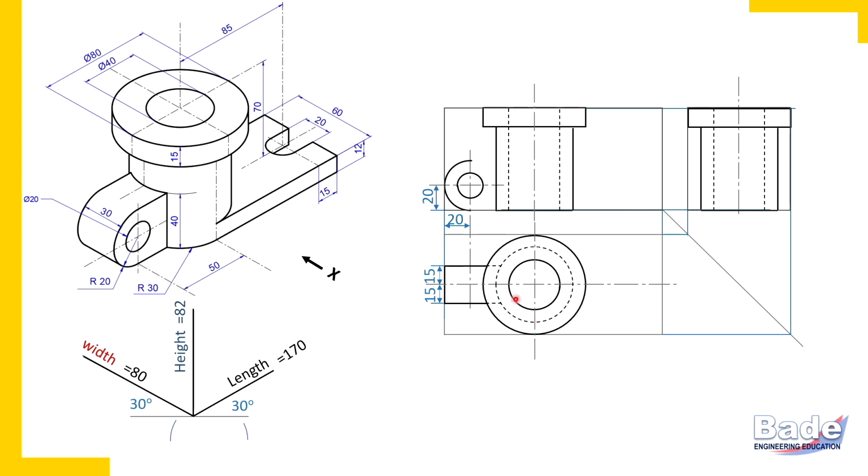Okay. Now check exactly where this U-shaped block gets connected or comes in contact with the cylindrical surface. Watch that sharp corner here, and a corner represents an edge in the opposite side view. So from this corner, check the horizontal dotted line here and the circular dotted line where they meet, that corner, draw the projector.